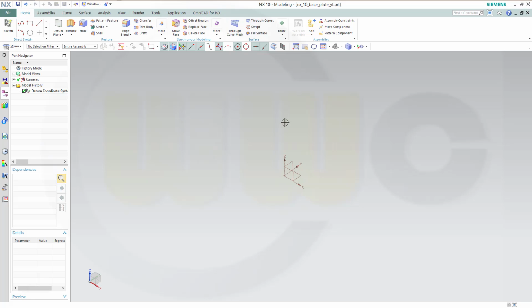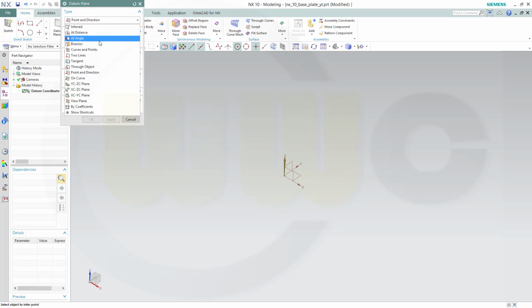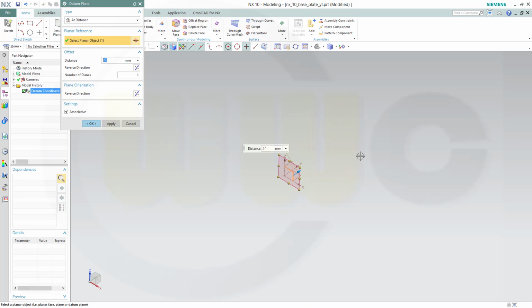I want to do the base plate which I did before in CATIA. So first I need some planes. Add a distance. First one should be at 400. Next one should be at 600. One at 1050. And one at 1500.